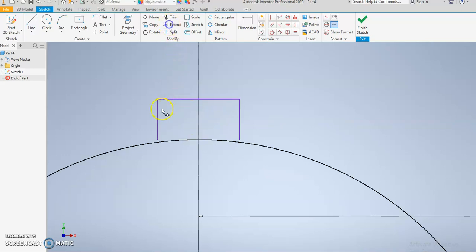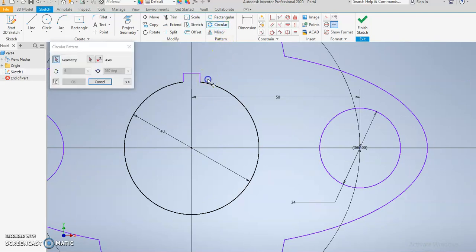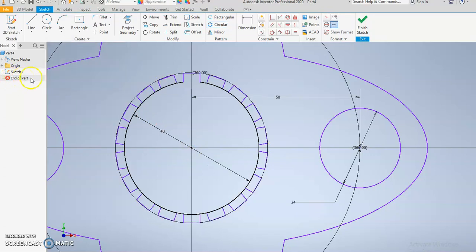Then I would just do an extend to the bottom. You have to do this part, otherwise you can't trim it. Okay, now if I want to, I can trim that real quick. So one final array and then extrusion, and you're done. And with some trimming. So next we're going to do a circular pattern. I'm going to click these here, choose geometry, click the middle. And there is 18 of these. I put it on your sheet, make your life easier. And there we go. Trimming.